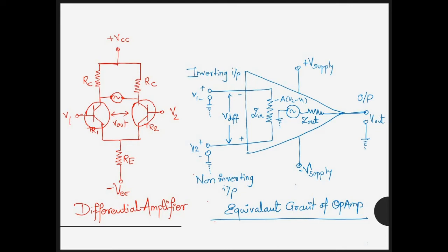The first one is the voltage follower, where Vout equals Vin. Then the next one is the op-amp as an inverter. The third one is the non-inverting amplifier. The fourth one is the inverting amplifier. The fifth one is the bridge amplifier. The sixth one is the voltage adder. The seventh one is the voltage subtractor. And the eighth one is the comparator. All the above are the lists. So one should take into account the configuration with reference to the connections and the feedback paths and so on.